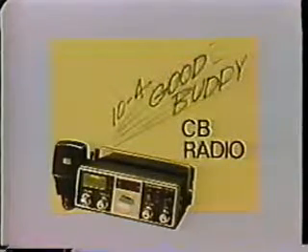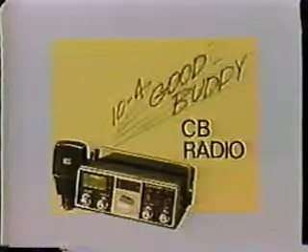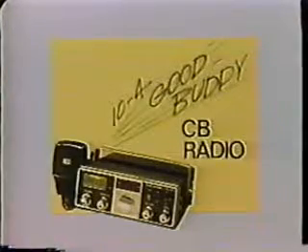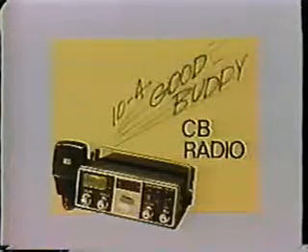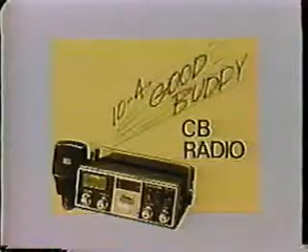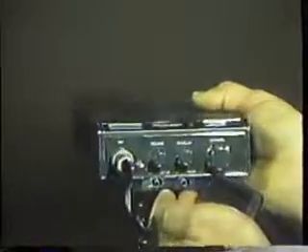The crystal keeps each channel at its proper place so it will not interfere with adjacent channels, and so that each radio set will broadcast and receive at the same frequency. It would not be possible to communicate with other CB operators if the frequency of each channel was not accurately controlled. If we have several channels, we can use a separate crystal to control the frequency of each channel, and this is often done.